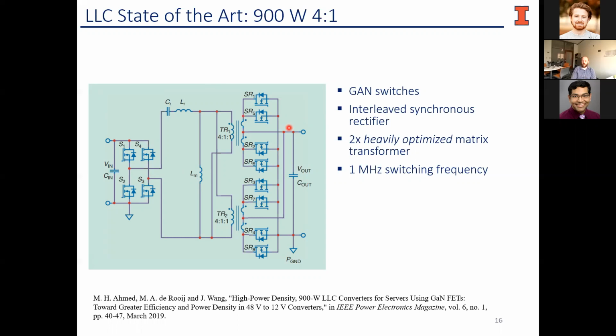And it's switching at 1 megahertz. It's important to note that all of these switches are switching at 1 megahertz. And that's where it's very important that they maintain that zero current switching in many cases and zero voltage switching.